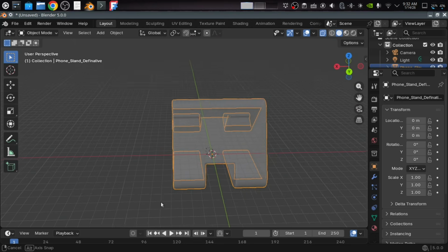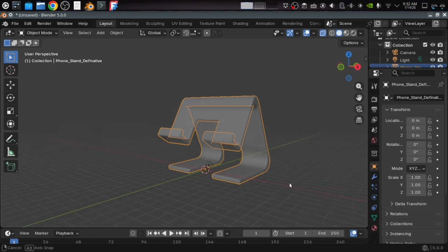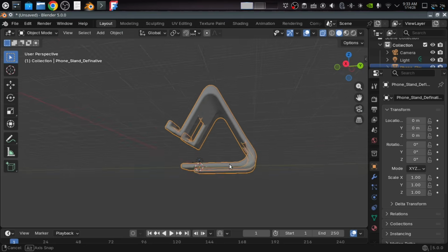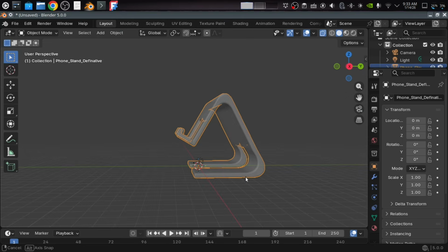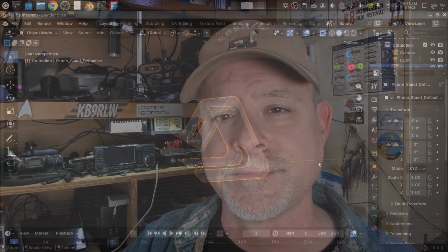Two quick operations in Blender. It's that easy. Blender's designed to work with these big, complex, and heavy meshes. So it makes it simple to work on these things. There's sculpt items and all kinds of options in Blender. It's really the best tool for modifying STL meshes. If I wanted to put holes in things, I could add a cylinder. I could do a Boolean cut, just like you would do in Part in FreeCAD. Very quick and easy, and it has no trouble dealing with huge, complex meshes.